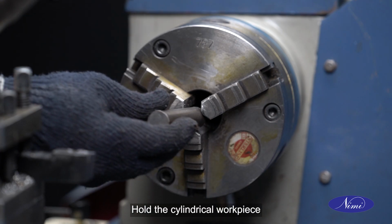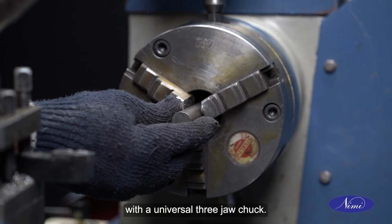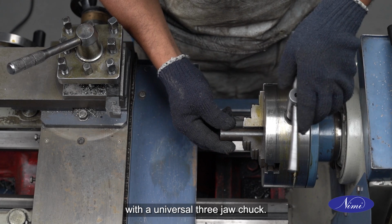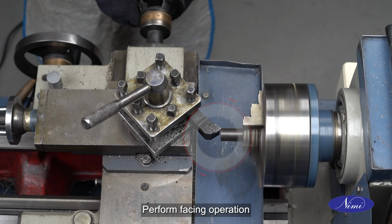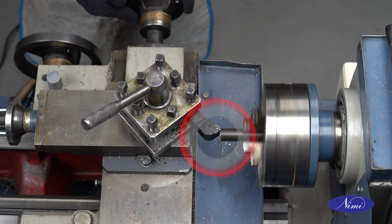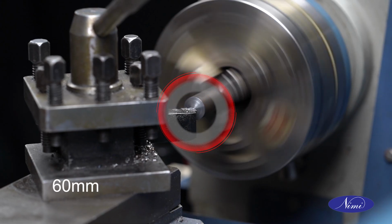Hold the cylindrical workpiece in a center lathe with a universal 3-jaw chuck. Perform facing operation to maintain the length at 60 mm.